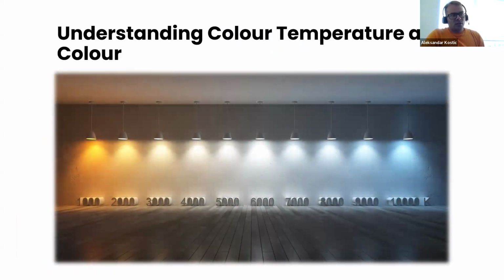So what is in general the control of the white color? We express the type of white color through kelvins and call it the temperature of the white color. The lower the kelvins, the more the temperature goes toward the yellow part of the spectrum, and the higher the kelvins, the more toward the blue part of the spectrum. Typically, LED tapes from Vibrant support a range between 2700 kelvins up to around 6500 kelvins. So we can completely cover that range of the white spectrum.